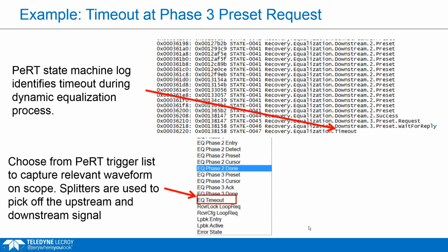If it's an embedded system where you just have some chips on a board and some lanes, it makes it harder from a test standpoint, but it's easier in general, because you can tune those equalizers for that specific system, and then you don't have to use any of this dynamic equalization stuff because the channel looks the same every time you power it on.